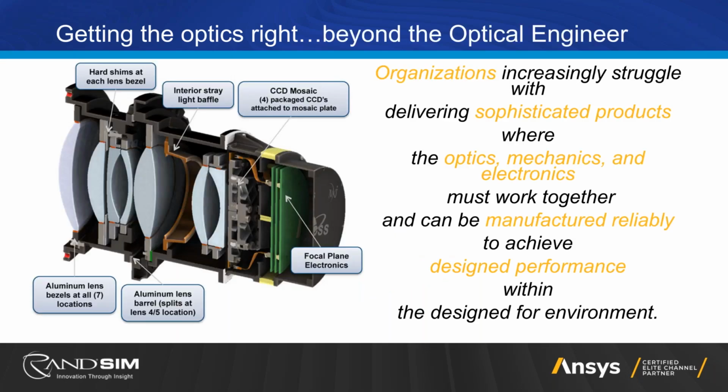When we look at the actual real physical applications of optics, it's never just the straight optical components. We also need to look at the mechanics and electronics that will impact the optics itself. So there is a need to see how the optics integrates with the rest of the system and optimize the structure together. And we also want to make sure that once the system is together, it will still meet the optical requirements specified in just the ray tracing tool. It's very heavy in the optomechanics space to make sure that the result is as intended from simulation to physical design.